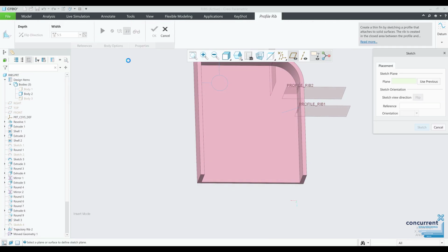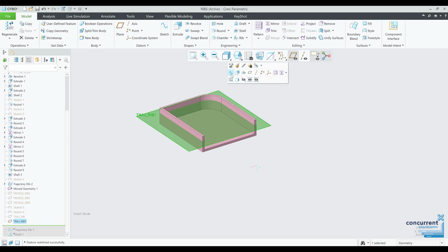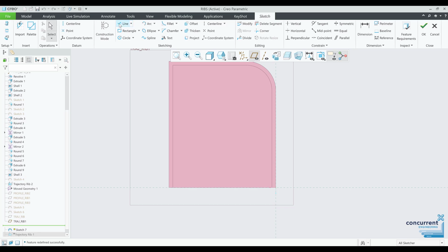I always think of it as dropping away from the sketch into whatever shape your design has. It's very simple to manage and it's fairly automated in how it behaves. I often describe it during training as being a little bit like a liquid that will flow normal from the sketch until it hits a solid wall, essentially following the curvature of your design, so you don't need to manually manage the boundaries. Usefully, you don't need to fully constrain your sketch, simply create these lines here and they'll automatically attach the rib to the internal walls.